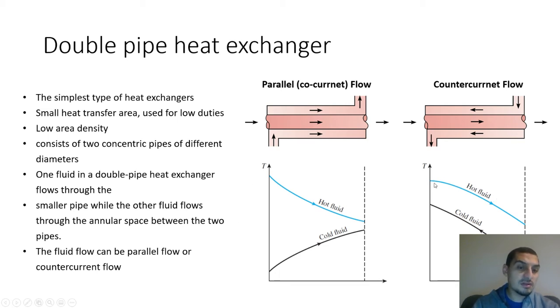but in the counter current you'd see that it's working the other way. So the hottest fluid is transferring heat to the highest temperature. So you'll have here good driving force, and here we'll have a driving force, and this is the beauty of the counter current: we have continuous driving force all over the heat transfer area.